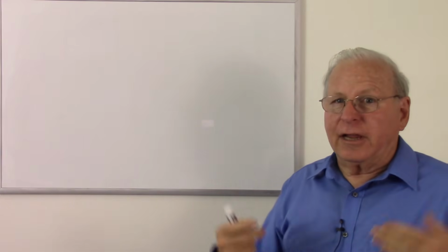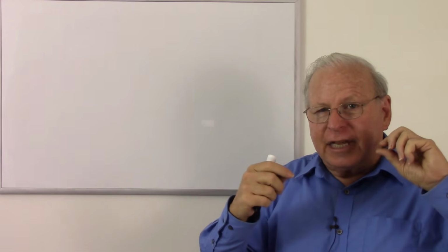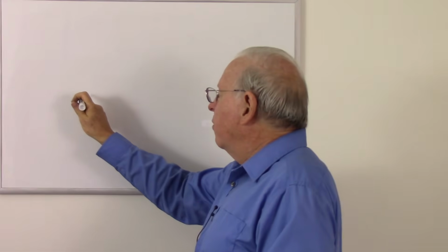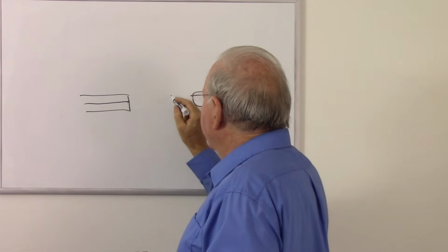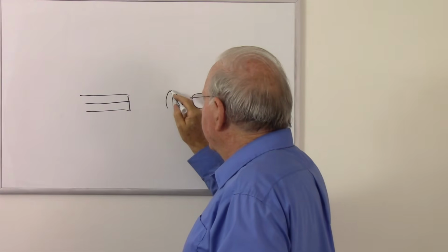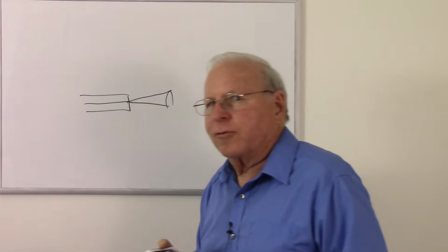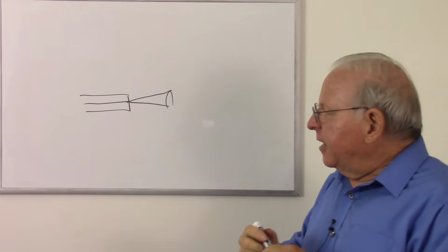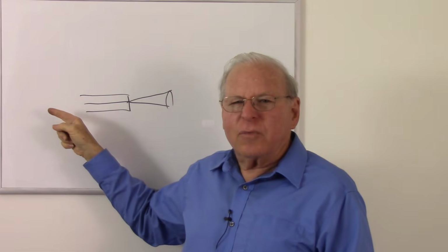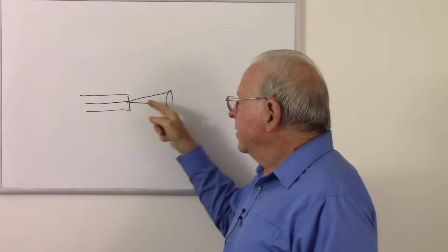And this is basically a laser pointer, except it has a lens that focuses the light right on the core of the fiber. So there's your ferrule, your fibers right in there, and we have basically a laser with a lens that focuses right on there. I tried this with a laser pointer. It doesn't work. You have to get that light focused in there properly. And you get that visual laser, usually red laser. I've never seen a green one, but could be.